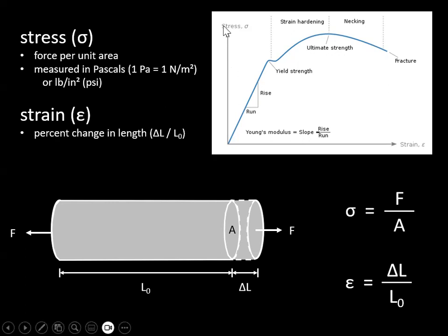So what is the relationship between stress and strain? Well, that's what this graph is right here. I say more stress, more strain. It tends up and to the right. The more stress you apply, the more it strains. Now, the first part is this direct relationship. This is called the elastic zone. You guys see this elastic zone right here?